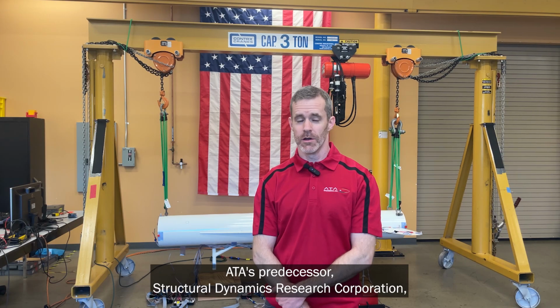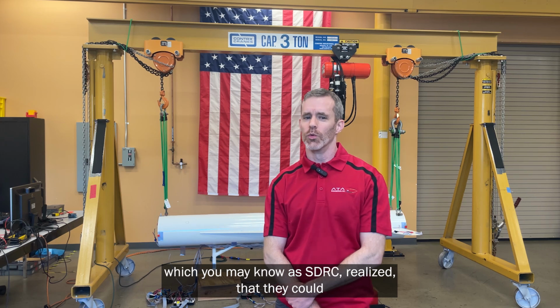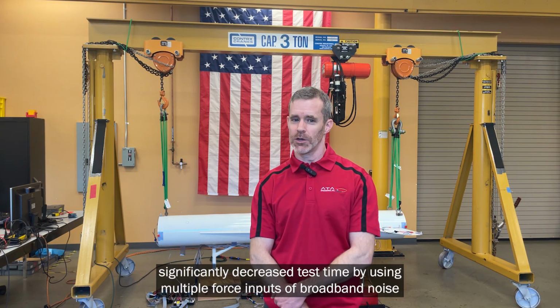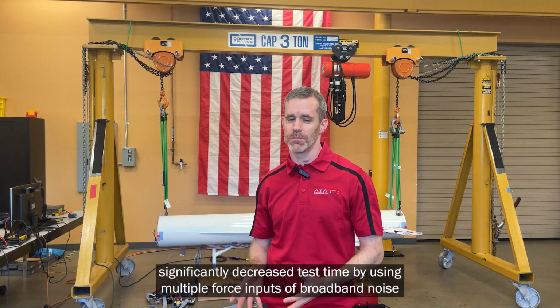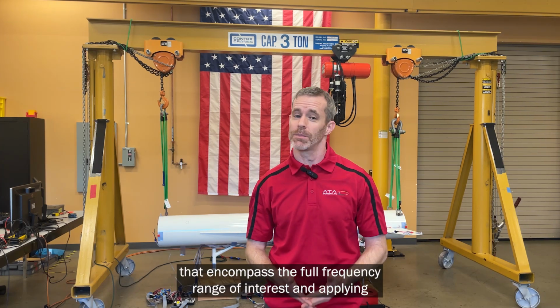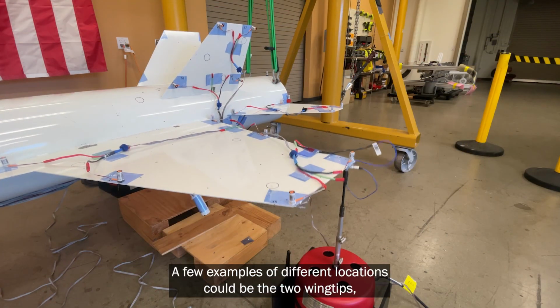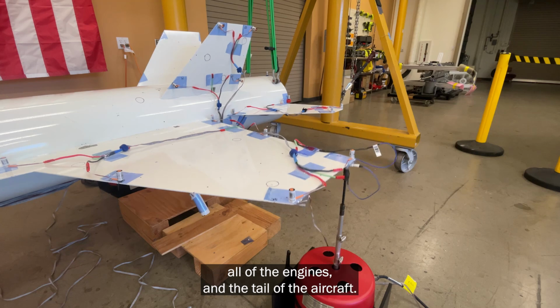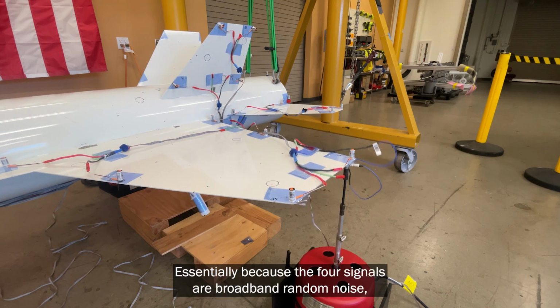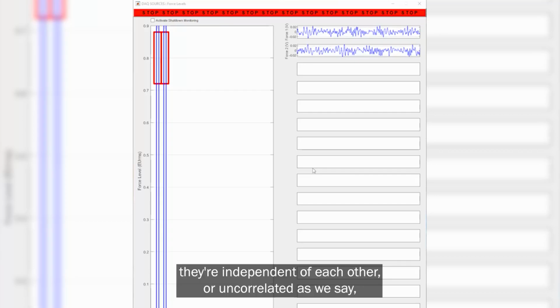ATA's predecessor, Structural Dynamics Research Corporation, which you may know as SDRC, realized that they could significantly decrease test time by using multiple force inputs of broadband noise that encompass the full frequency range of interest and applying them at the same time on different locations on the aircraft. A few examples of different locations could be the 2 wingtips, all of the engines, and the tail of the aircraft.